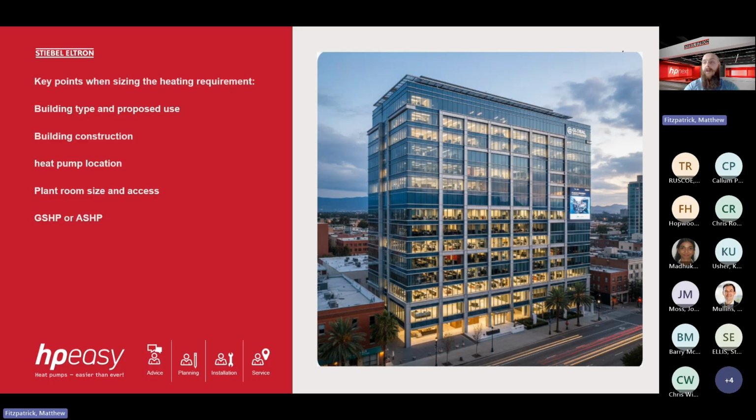If we look at gyms, sports halls, any area where we have mixed use, so that could be a sports area with showers, but there could be offices above, then we'd need to see the best solution. Now, it could be that an open sports hall, 3.5 meter ceiling height with gas blowers, and then 50 to 60 square meters of office area. Well, it's probably best through what we call a split system.